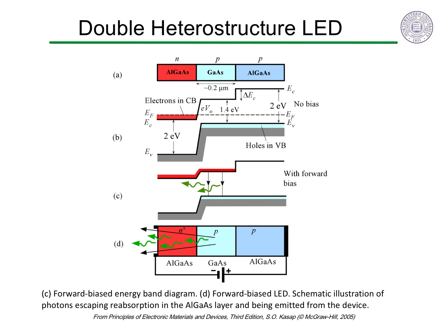We also have to consider the metal interconnects as well, because metals will typically reflect or absorb light. On the back side, we actually want a metallic reflecting electrode to reflect light that is produced heading to the right. Especially in organic LEDs or OLEDs, a transparent conducting oxide, TCO, is used for the left electrode to supply electrons but allow visible light to pass through.